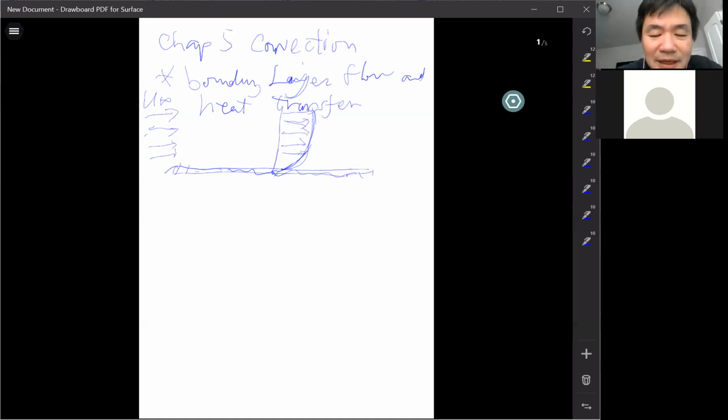But when it's very close to the plate, obviously you feel the presence of the plate, right? Because we're dealing with a viscous fluid, you have a viscous effect. It's called the no-slip boundary condition. Usually, when the fluid reaches a surface, it sticks to the surface. Exactly on the surface, there's actually no flow. Look at the flow distribution. We talked about this when we discussed viscosity; remember, we used this example. Exactly on the boundary, there's no velocity, but very far away from the boundary, there's the free stream velocity. So in between, there will be a gradual change.